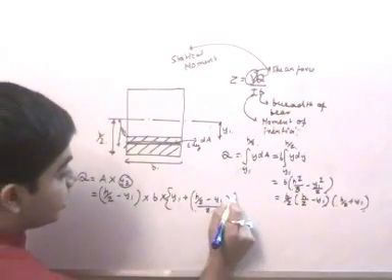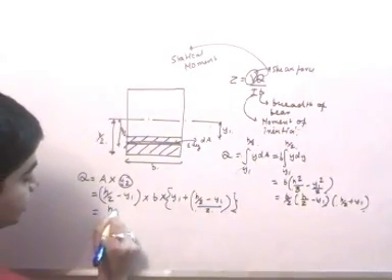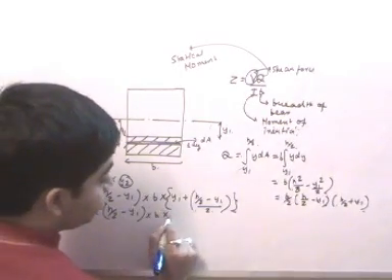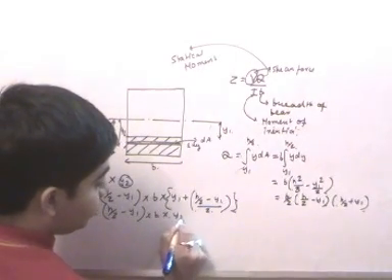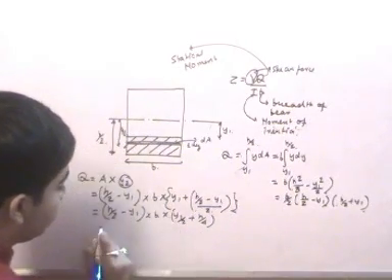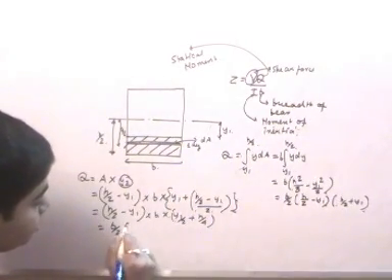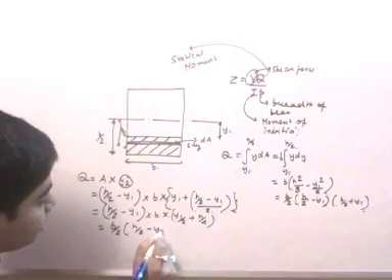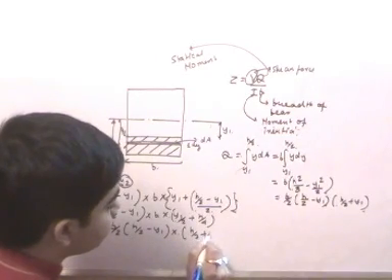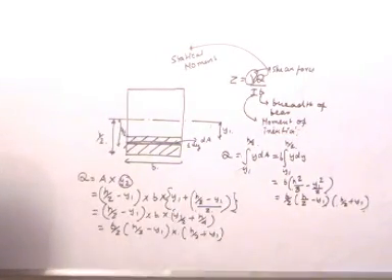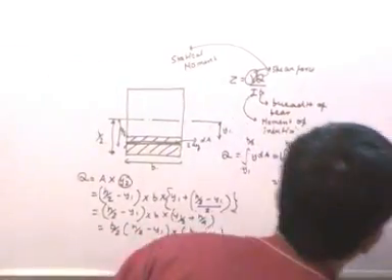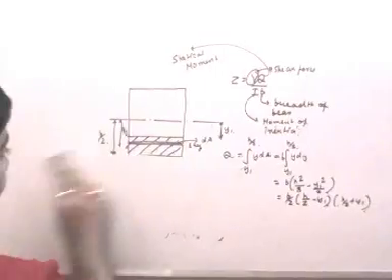So this is my Q, and this is equal to h by 2 minus y1 into b into, this will be y1 by 2 plus h by 4, or it will be equal to b by 2 into h by 2 minus y1 into h by 2 plus y1. So this is what represents the statical moment for a rectangular cross section, and it will be obviously different in the other cross sections, right?